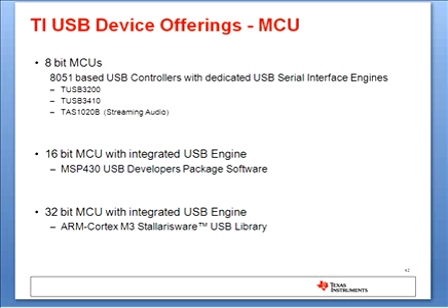TI has a wealth of USB silicon for developing USB applications. For MCUs, we have 8-bit, 16-bit, or 32-bit MCUs. Our 8-bit MCUs feature the 8051-based USB controllers with dedicated USB serial interface engines. Some examples of 8-bit MCUs are the TUSB3200, the TUSB3410, and the TAS1020B.